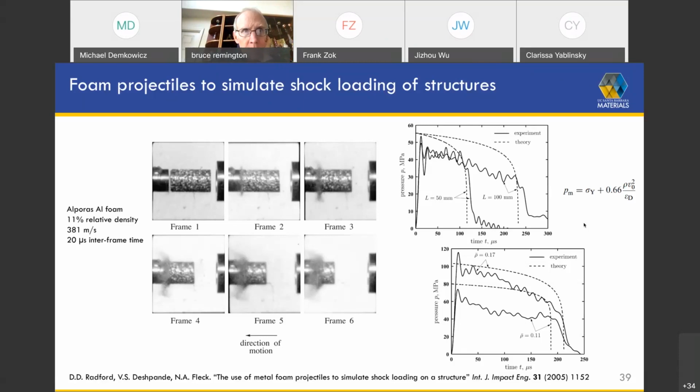Assuming that your strain gauges are reliable, and that's the main thing, right? I mean, if the strain gauges are reliable and the system is well aligned, I mean, the system has to be, of course, very well aligned, then the results should nominally represent the range of real material behavior. Okay? And so one shouldn't rule out the possibility that variations in measurements are real. Okay?